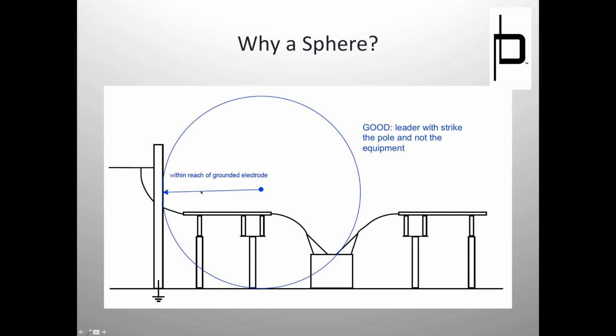Right. All right. Why is that? Well, a number of different reasons. Some say, well, it's higher, it's grounded better, things like that. Another key point is that this bus is separated from ground with this insulator, right? So this is not a grounded object. To get to ground, not only does it have to traverse all this air and all the resistance up to here, it also has to get over the resistance of this insulator. Whereas here, it doesn't have to get over that resistance, right? So if given the choice, it's most probably going to strike this. Yeah. Right. Makes sense. Yeah.